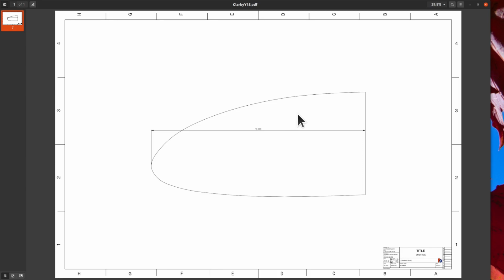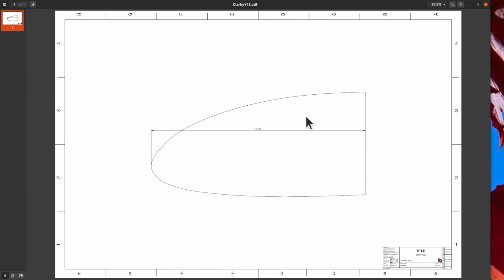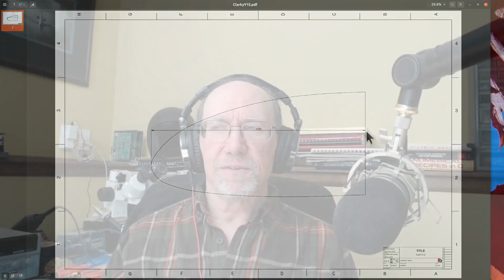Now a really crude thing to do then would be to tell your printing machine to scale to 101%. That's not going to be exactly accurate. It'll be off by 0.1%. Then you print it out, do another measurement, and it should be pretty darn accurate. Now I'm not an expert on FreeCAD, so there could be better ways to do it, faster ways to do it. But at least this does get the job done.